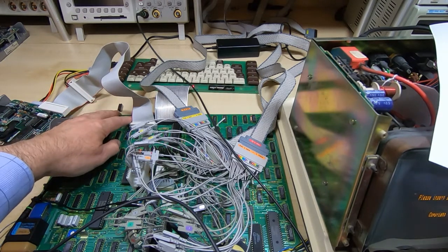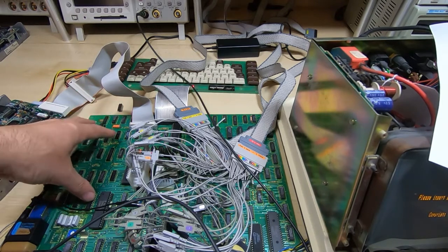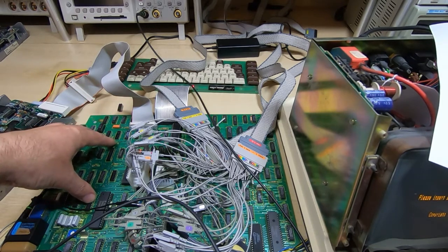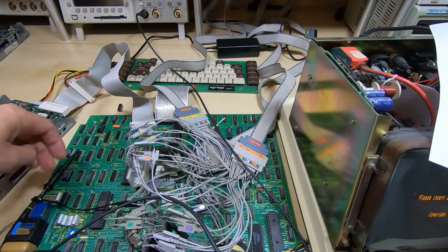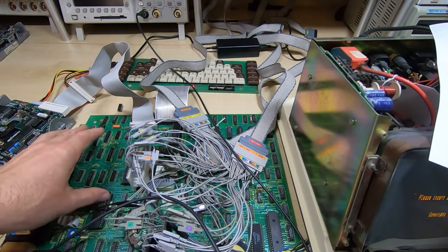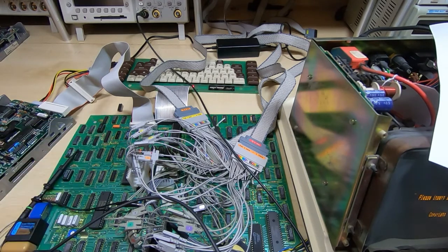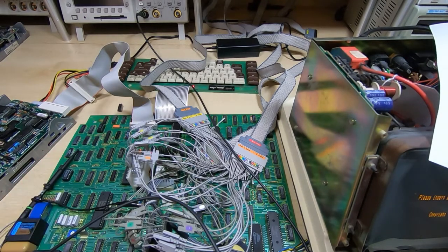So I've replaced that device. I found a broken track as well. The track issues on this board are fairly bad because of the location of the battery, and when it fails it tends to do a lot of damage to the board. So I had an open track as well, so I've also fixed that. So we'll now look back at the logic analyzer and see if we've made any further progress before we go back into more detailed analysis of the board map layout.